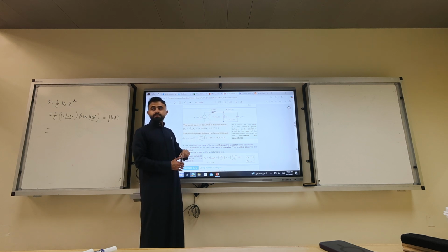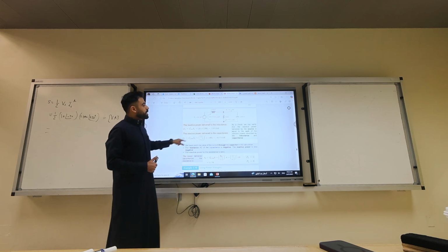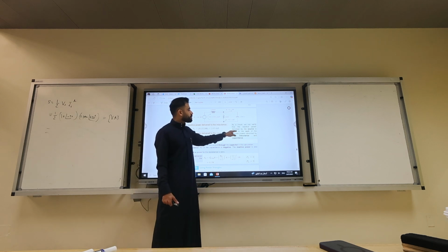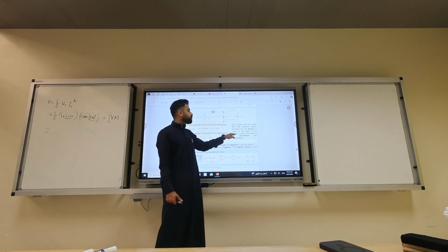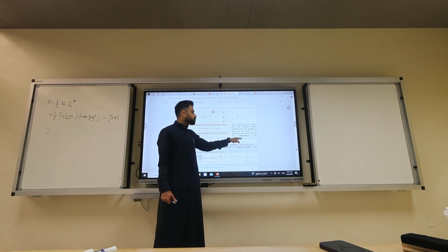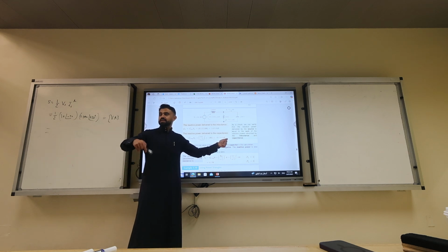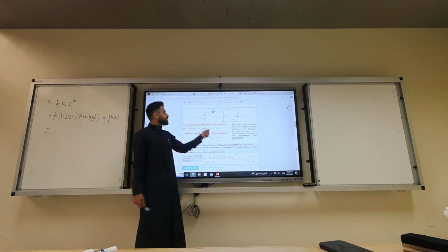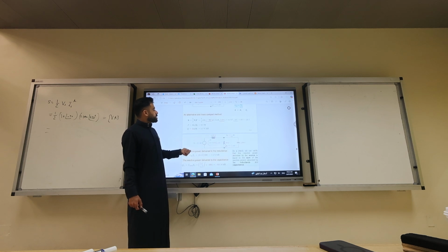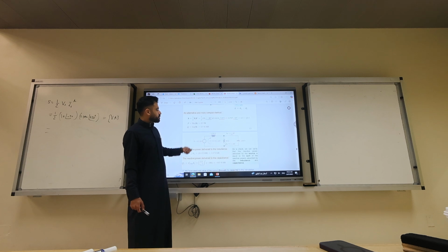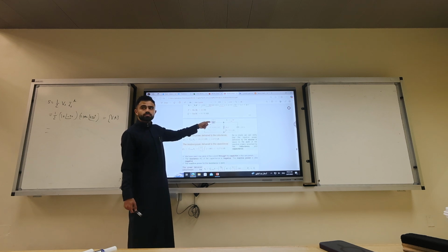Now, we can verify that the reactive power delivered by the source is equal to the sum of the reactive powers absorbed by the inductance and the capacitance. The capacitor absorbed minus half, which means it supplied plus half. The source supplied 0.5, and it all went to the inductor.